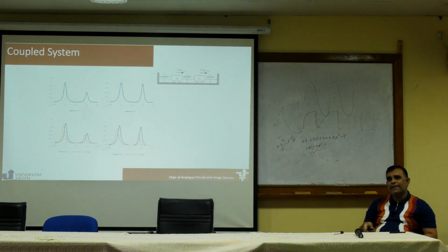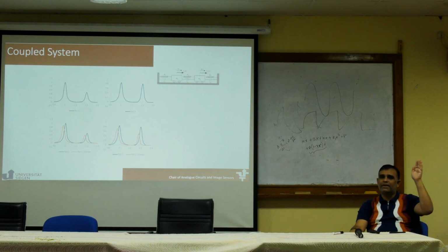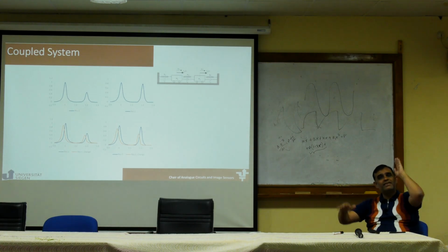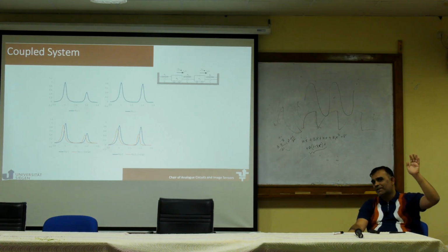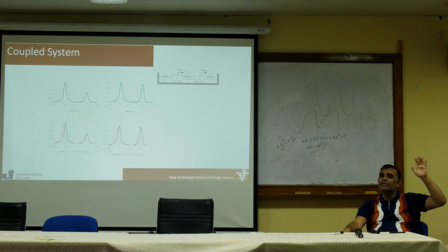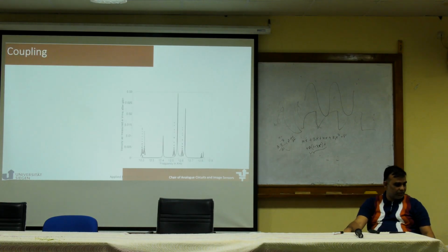Essentially, if I have an array of resonators, I can measure the entire resonance frequency from the response of the first resonator. Then if my fifth resonator changes, by measuring mass or stiffness or something, the entire eigenvalue of the system will change, which I can still measure from the response of the first resonator. So I can have an array of sensors and just measure it by the response of one resonant system. And I will show it to you here.